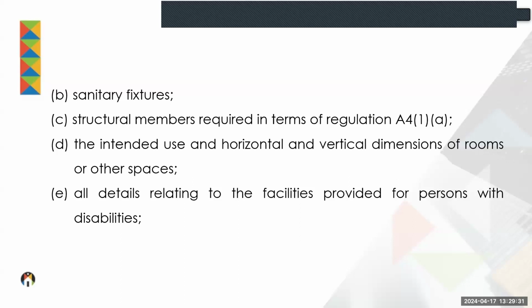not just to go and check because that's on a checklist, but we need to see everything holistically. In other words, if you have to provide accessible facilities, make sure that it can be reached. In other words, that the building is actually accessible as well. And for that reason, go and look at passage widths, door widths, etc.